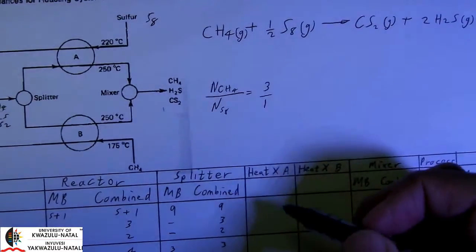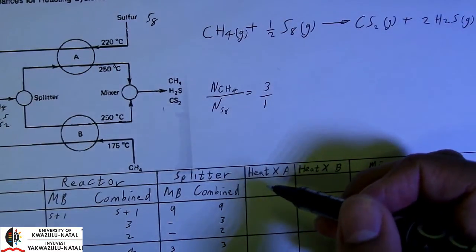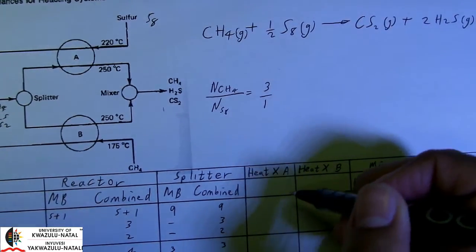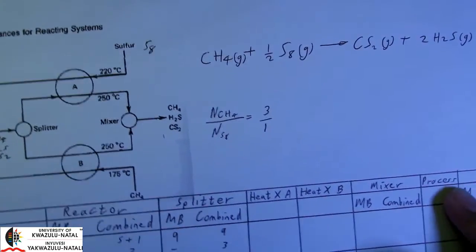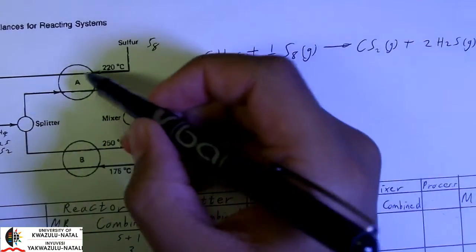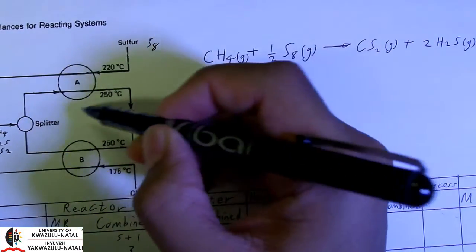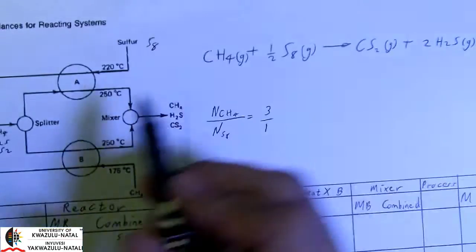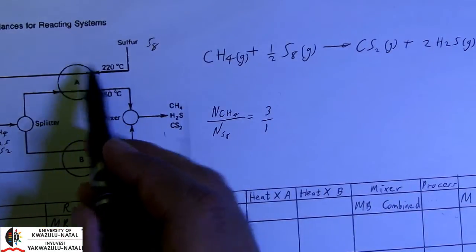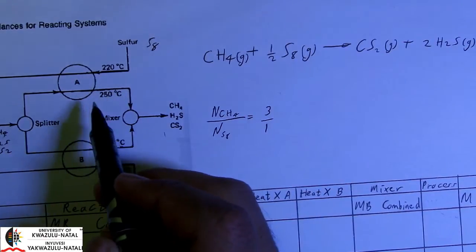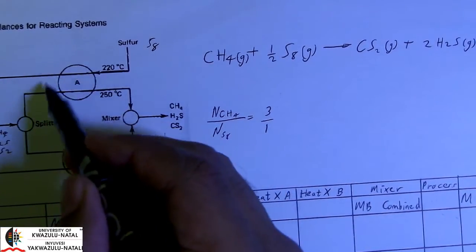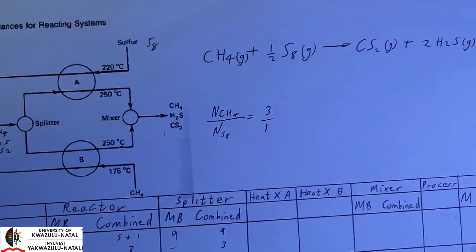Okay, in terms of our heat exchanger, there is a special way to handle heat exchangers. So pay careful attention. When it comes to counting the number of stream variables, in the case of a heat exchanger, we don't count every variable in every stream. Instead, we count the maximum number of different components.